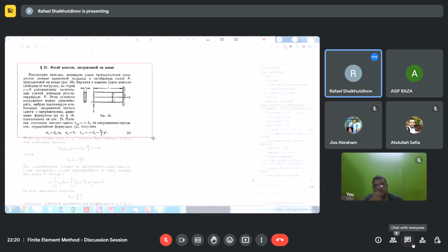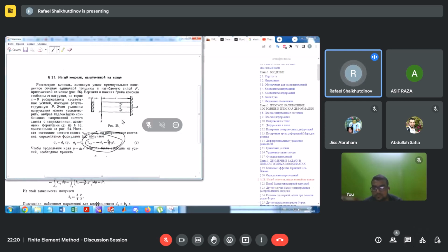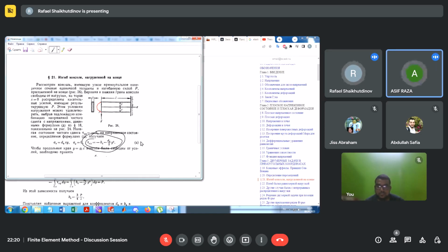What I see today when I consider this problem: always tau is present when we have a shear force. When we have transverse force, there is always tau distribution along y, and it is parabolic, the well-known distribution of the shear tau xy.